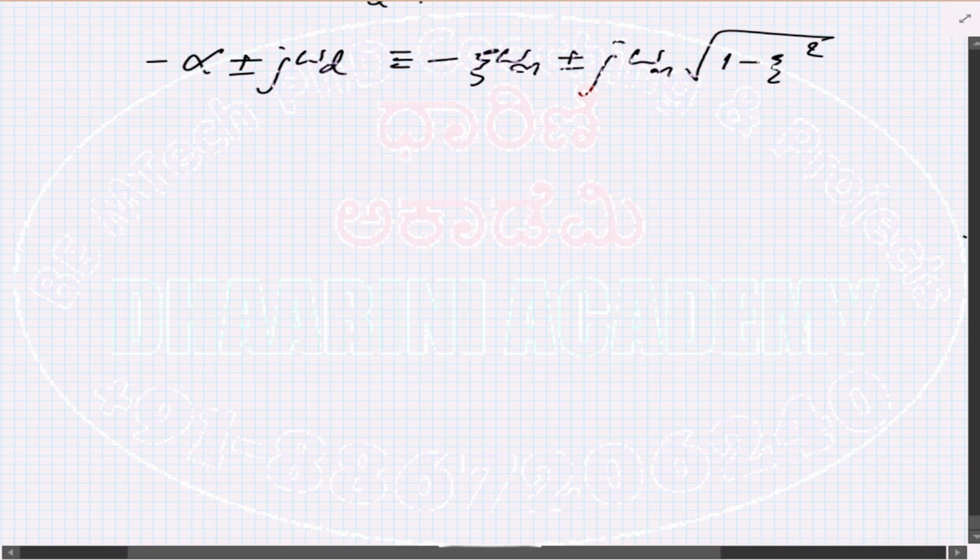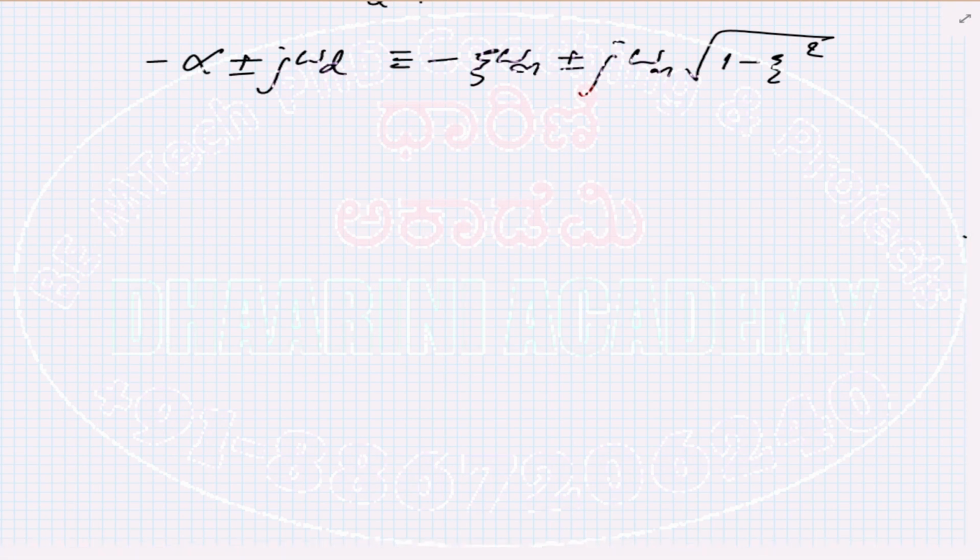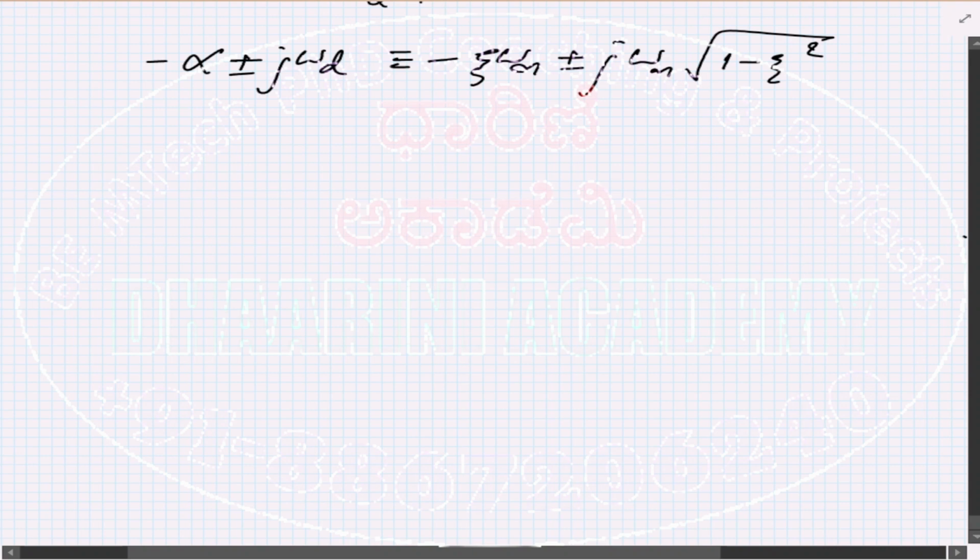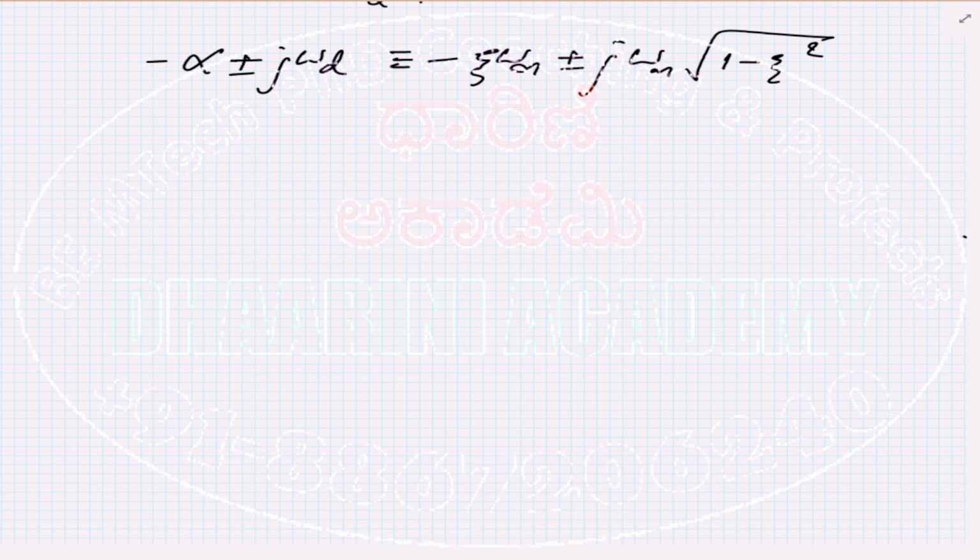If you remember the basics we studied from physics, it says that every body has its own natural frequency. It's something like, you try to give an input of that frequency, it tries to respond back to you with the same frequency. It only happens whenever it's something similar to the resonance part. So we know that omega n is fixed for a given object or given system. Zeta is the one which we can change whenever we want to design something. Considering that, now let's look at a graph.